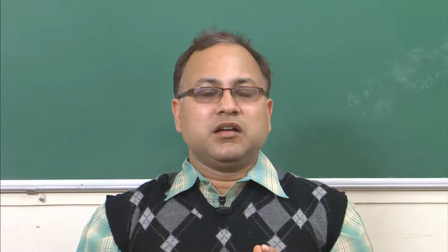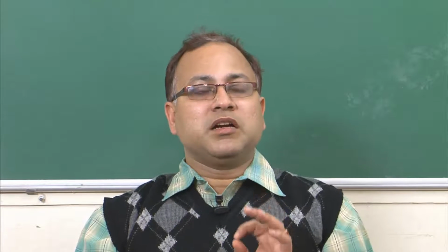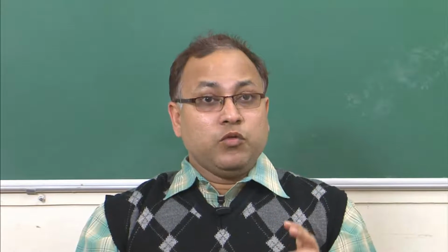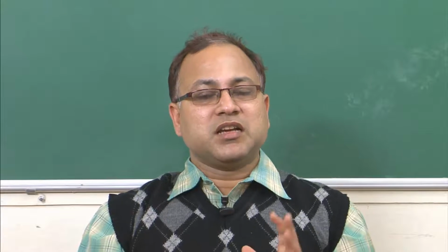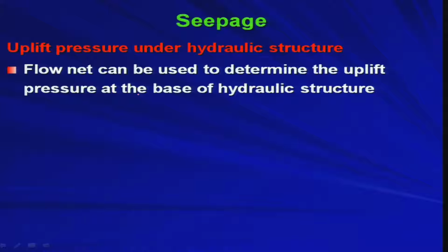Already you have seen that whether you consider square elements or rectangular elements is not the matter of fact, but the main thing is that you are getting the rate of seepage. But you can get other information from the flow net. So, what is that other information? That is that you can determine the uplift pressure under the hydraulic structure by constructing the flow net. Now, we will see how we can do that.